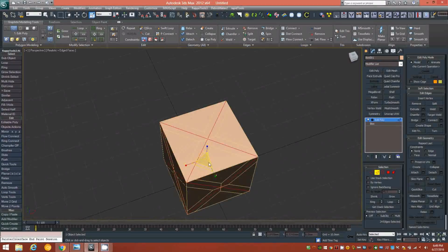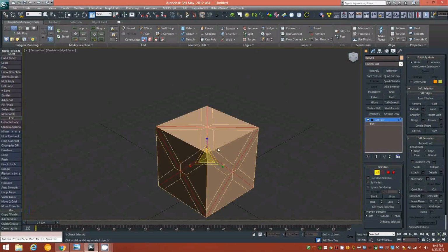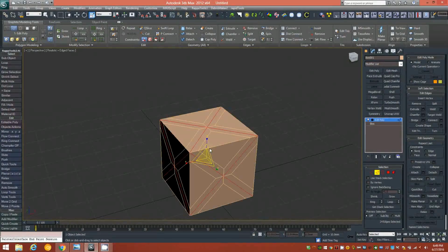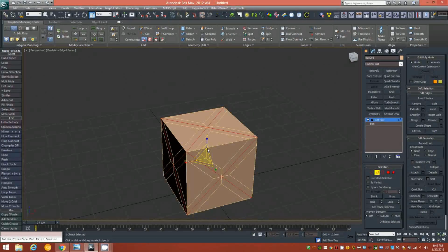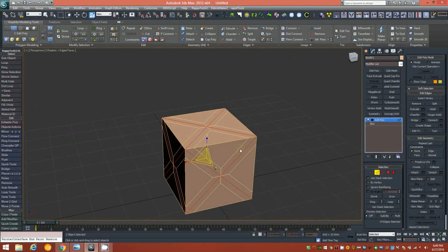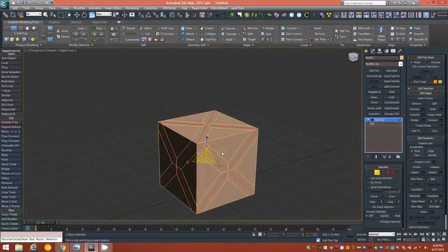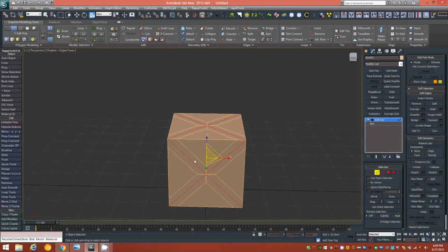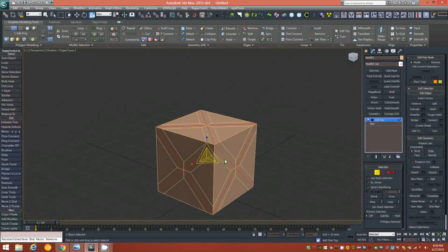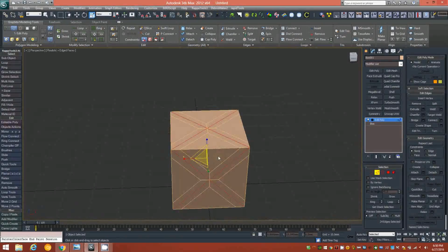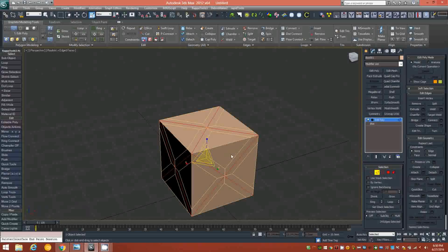You can feel free to experiment on your own to see what difference the chamfering would have given you on those edges, but rest assured that this is the result we want with the extrusion. It's an equidistant edge extrusion without any height. Chamfer would have given us a much different result, even the quad chamfer.